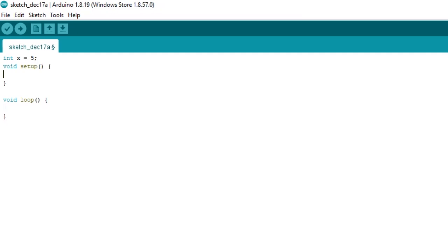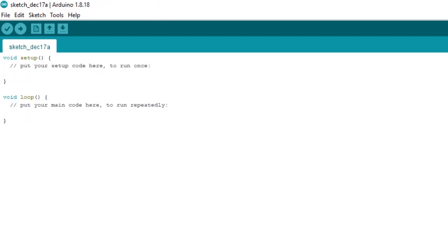After creating the variable, we have to write the type of information, which we write using the pinMode code. In parentheses, we write the pin number or the variable to which we assigned the pin number we want. In our case we will take the variable. After writing this, we definitely put a comma and write the type of information. The one that gives information is output, and the one that takes information is input. In this video, we have two codes left to study, one of which we will learn right away on the project. We need to make the light blink.